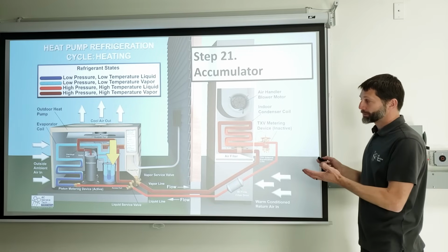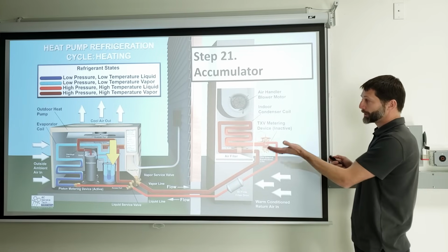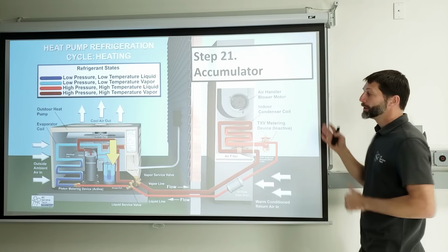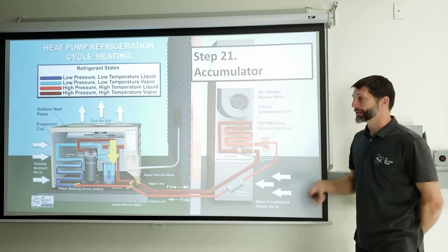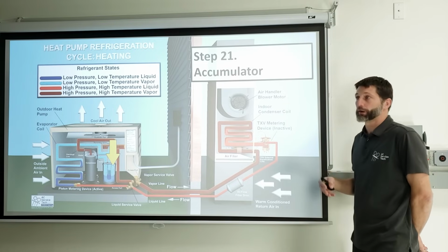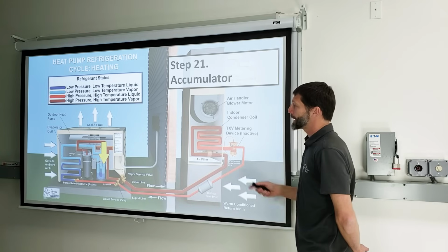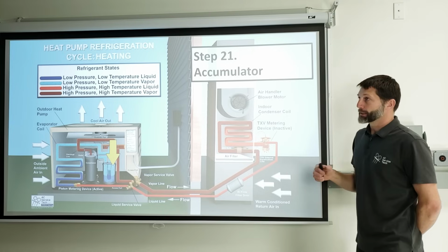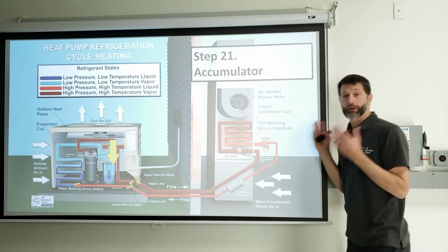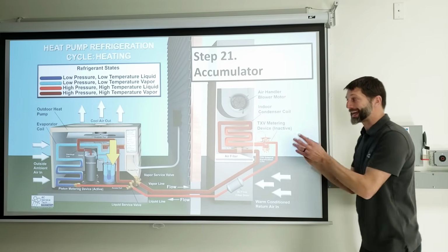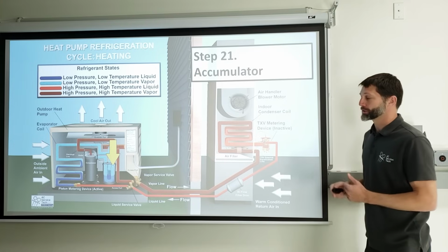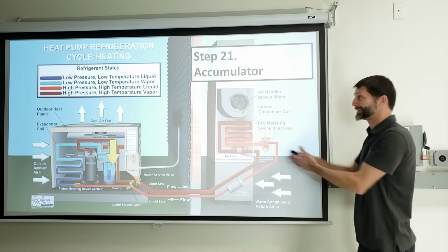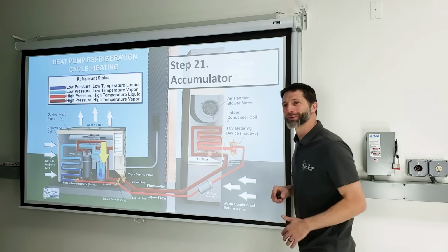When we're running an outdoor unit, like an outdoor ducted heat pump, you're only going to be able to run it down to a certain temperature, and then you may have to switch over to some other auxiliary heat source. It's just a matter of how efficient your defrost controls are on your outdoor unit. A mini split unit runs very, very efficiently with its defrost at the outdoor unit. It runs very efficiently also with absorbing heat energy at that indoor coil because it's not ducted. But that's a whole other subject.